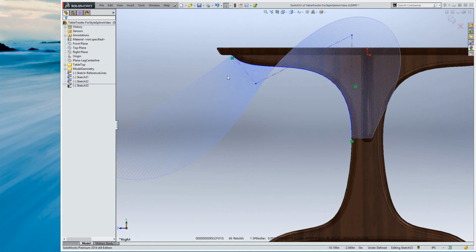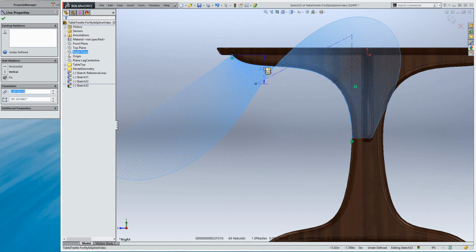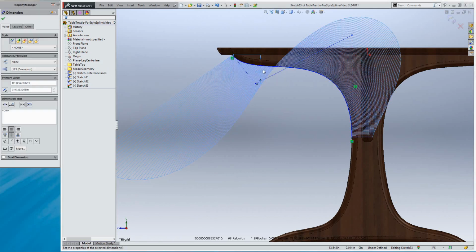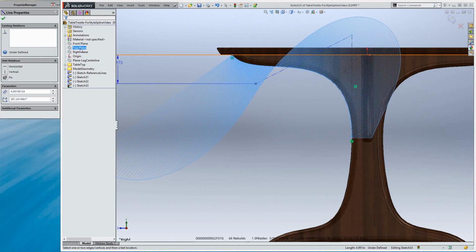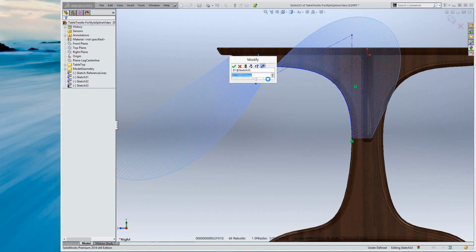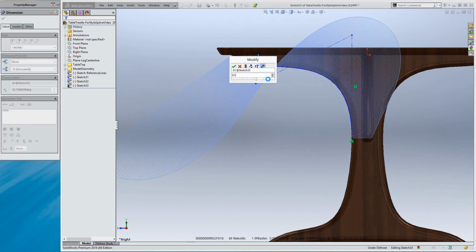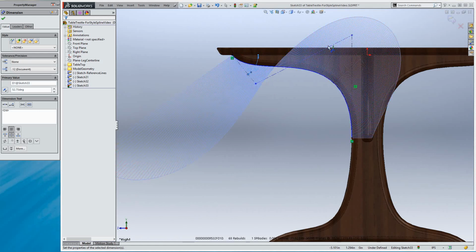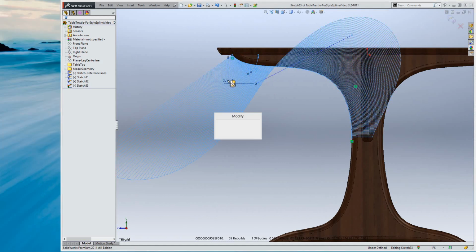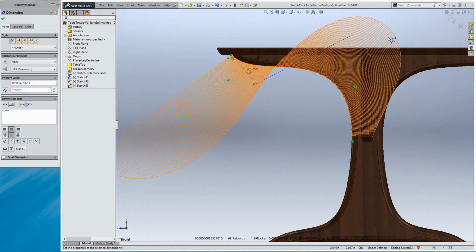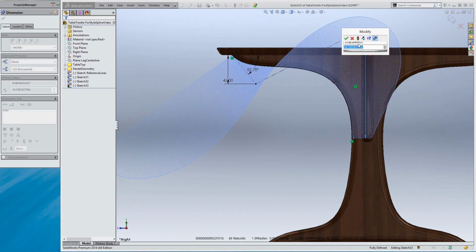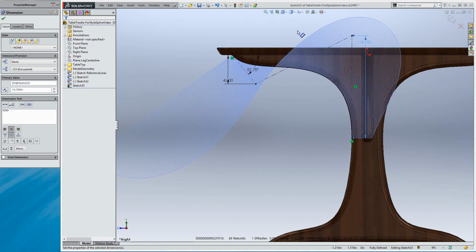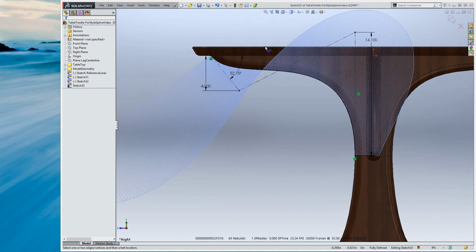Okay, now I can go in, and if I know what angle I want, or I want to make an approximation, I can, that was an angle, try again. Go ahead and go to the top plane this time and make an angle. 52.75, sure. And if we dimension this length here, we can dimension this length here, and these are kind of ambiguous, but they're dimensionable, and they're very predictable when we modify them and give us much more predictable results. If you've ever done it with splines, it's kind of crazy.